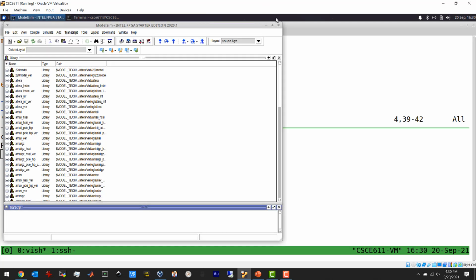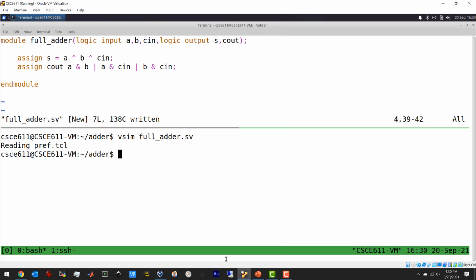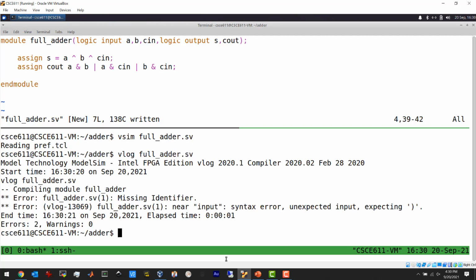Oh, sorry, not vsim, vlog. Scratch that. vsim starts the simulator. vlog compiles. Sorry, I was wondering why that was so slow. I don't know what the v is for, but log is for Verilog. There's also another command to compile VHDL, but vlog is the Verilog one. It works for Verilog and SystemVerilog, although there are some options you can add to define the dialect.